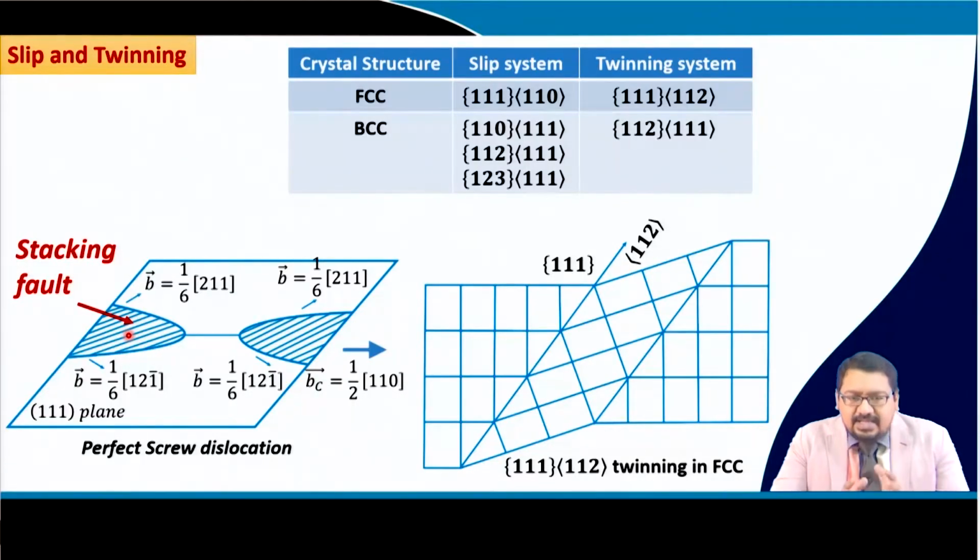So, in case of high stacking fault energy face centered cubic material, as the distance between the partials is lower, cross slipping of screw dislocation is possible, and this allows the material to deform with a multiple number of slip systems, and therefore, the deformation of the material is relative to the slip of dislocation slip in the material, which is basically 111, 110 type.